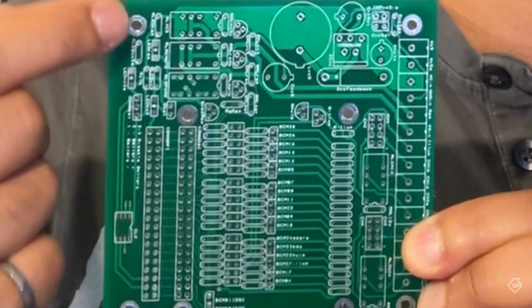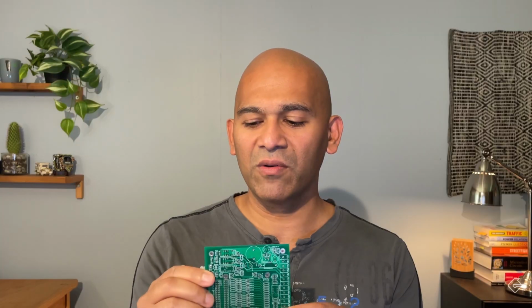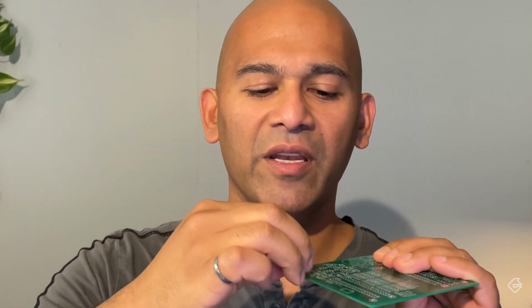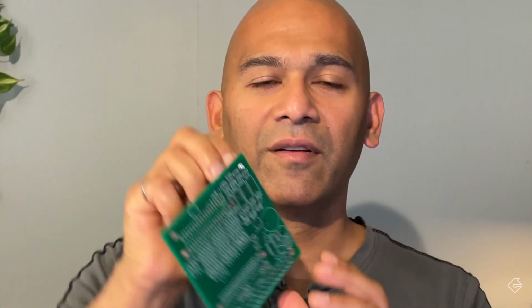This is a more recent printed circuit board that I had designed, and you can clearly see there are some screw holes, but you'll notice that these holes have a really big annular ring. In episode 18, I think it was, we talked about what an annular ring is, and it provides an electrical connection for whatever you're going to solder. But these are screw holes, and we're not soldering screws onto this PCB. I did put the annular ring in there because when you put a screw into one of the holes, the annular ring gives it a little bit of a buffer, because that screw head might touch other components on my PCB, and I certainly don't want that.